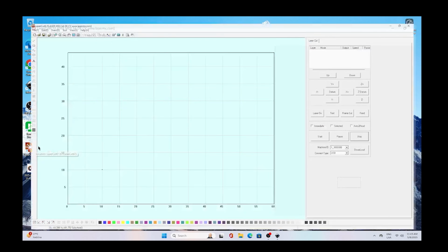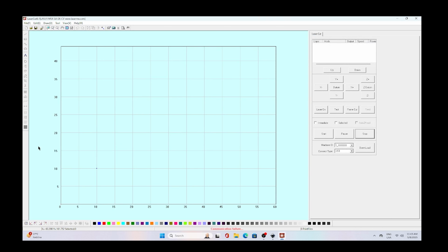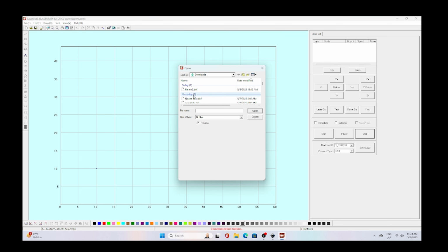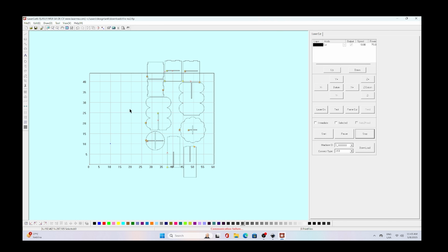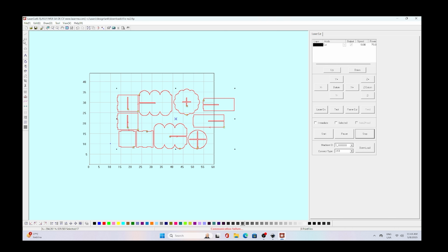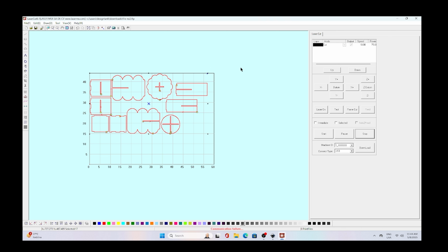So now we're gonna move over to our CAM software. In our CAM software, we're going to be adjusting different manufacturing parameters. So what we see here on the screen is actually the size of our bed. We're gonna import the DXF file. And here, more than designing, we can choose the layout of our cuts. So first we're gonna move that around with the arrow tool, and you can see more or less how much of our laser cutter bed we're gonna take.